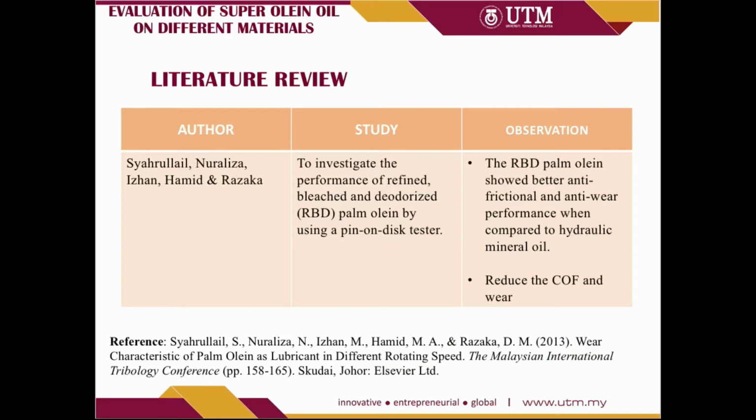Now, here are the findings that I have reviewed, where the authors investigated the performance of refined, bleached, and deodorized palm oil by using a pin-on-disc tester. They observed that the RBD showed better anti-frictional and anti-wear performance compared to hydraulic mineral oil. The coefficient of friction increased as the sliding speed increased for both lubricants, and this is because the unsaturated fatty acid played an important role in reducing the coefficient of friction and wear.